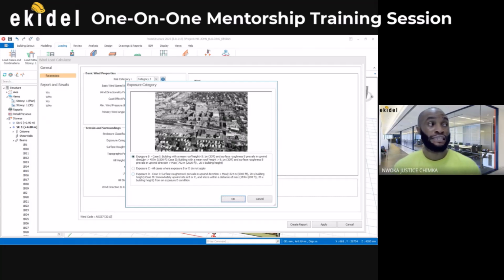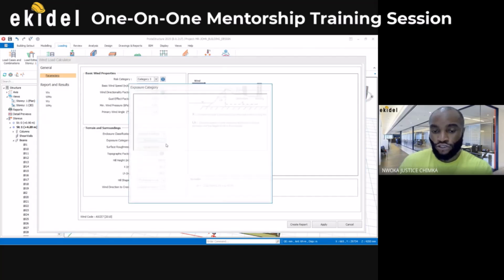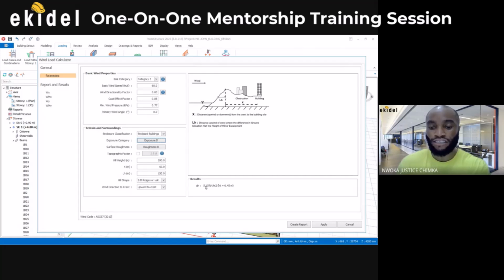So in this case, let me say we are building in a city. Then we can choose that and say okay. Now, if I make a mistake and choose D, you can see the pressure is now 5 point something. What it means is that at D, which is a desert or open area, the wind effect on the structure will be very high. That's why you can see the pressure has increased to 5.1. Are you with me? Yes.